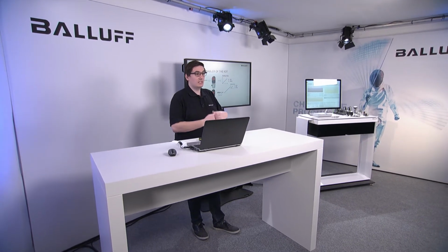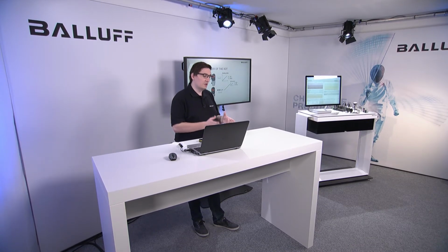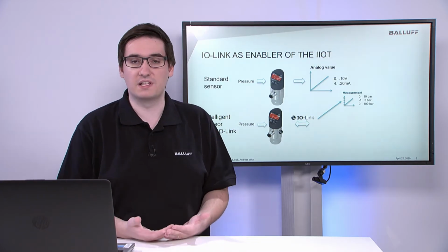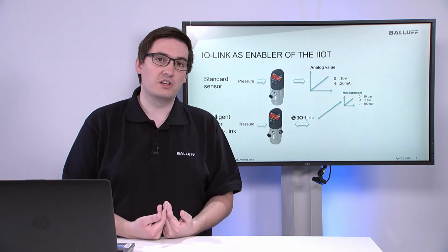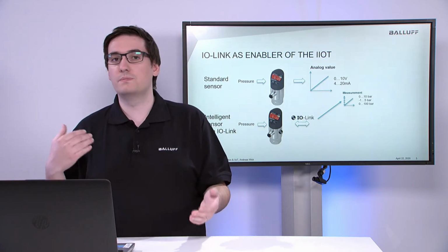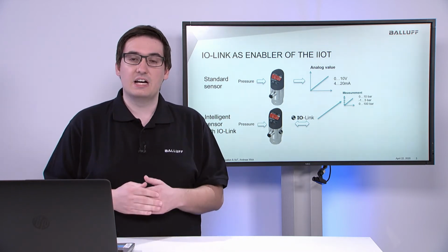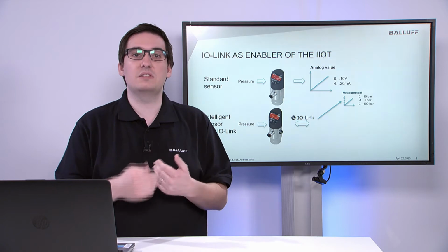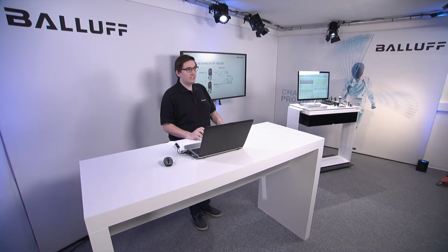So with this optical sensor, if the sensor pre-processes the data and already provides you with a parts-per-minute or switching-points-per-minute value, that is much more valuable for your application because you can use this value directly. It doesn't matter whether you pull this information once per minute or once per hour, because you don't have to calculate the parts per minute, you just ask your device for it.